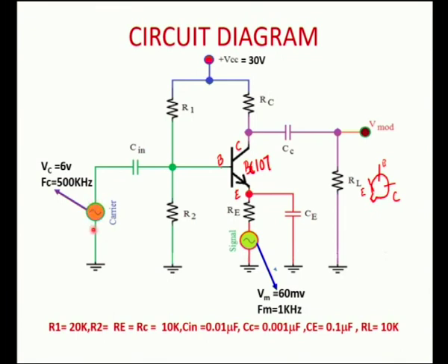The signal provided by this function generator will act as a carrier signal. So, this carrier voltage should be much greater than the message voltage, in order that the modulation index will always be less than 1. Okay. So, for that you can have this in some volts. This can be in the voltage range, this can be in the millivolts range.